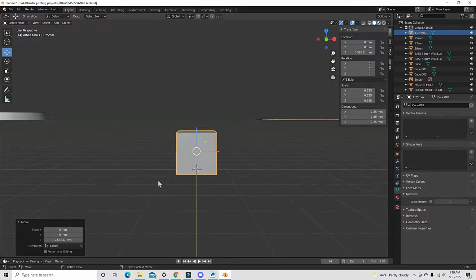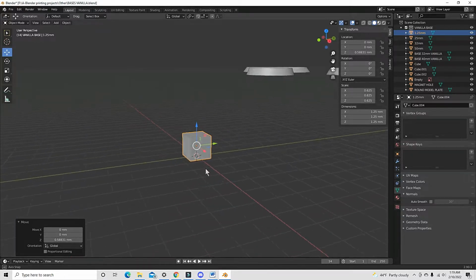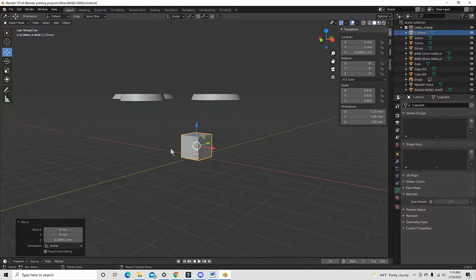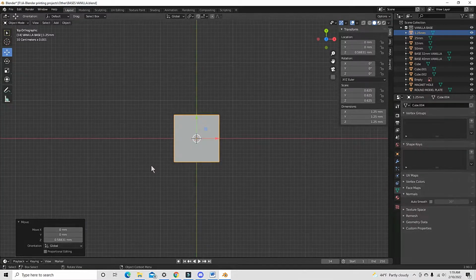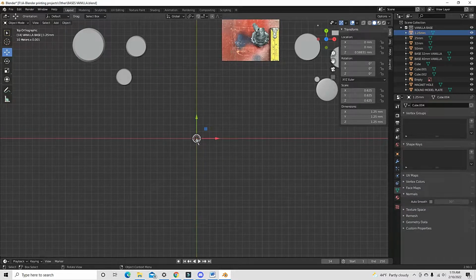Let's say there's an eagle or flat thing here, and then there's a little embellishment on it, it has to be 1.25 to really show up on the model noticeably. Things in between may not print at all, or you might not even notice it with your own eye. So you have to be aware of these limitations. So 1.25 is one of these.